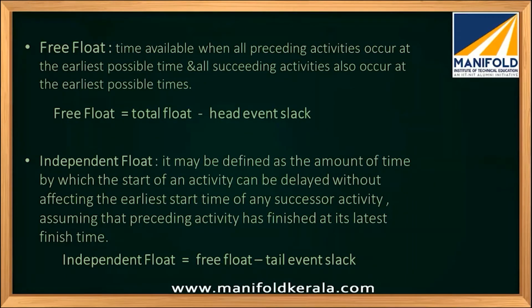Similarly, independent float can be defined as the amount of time by which the start of an activity can be delayed without affecting the earliest time of any successor activity, which assumes that the preceding activity has finished at its latest finishing time. So independent float is nothing but free float minus the tail event slack.